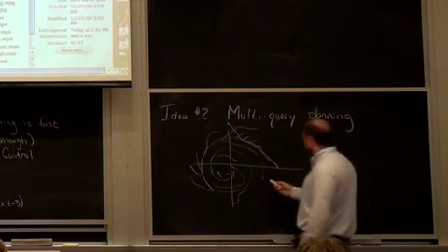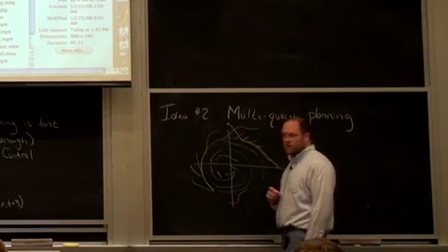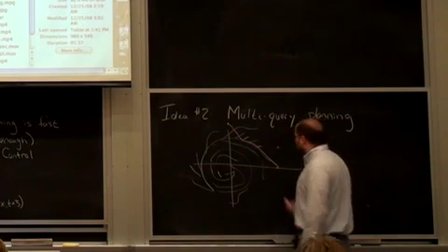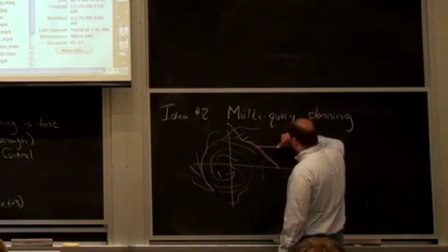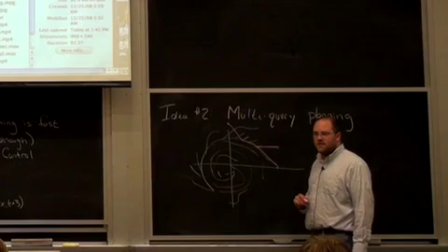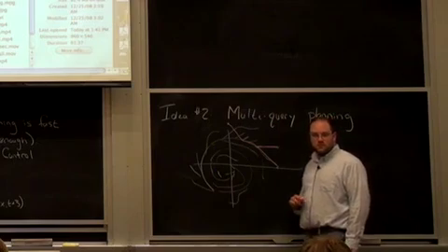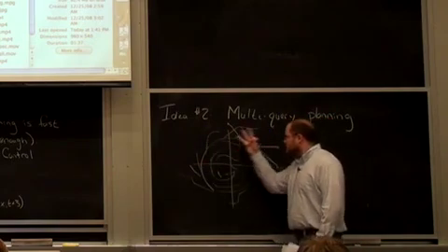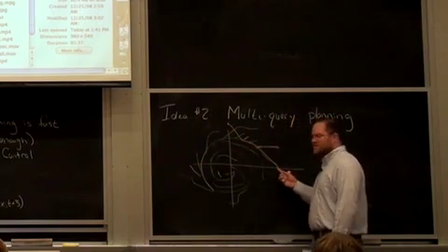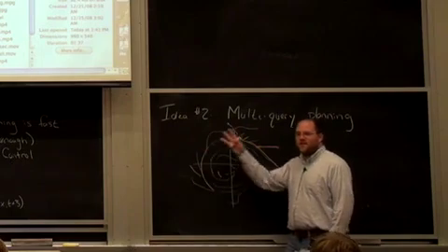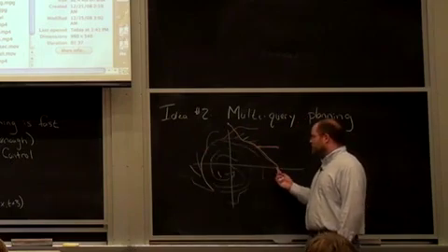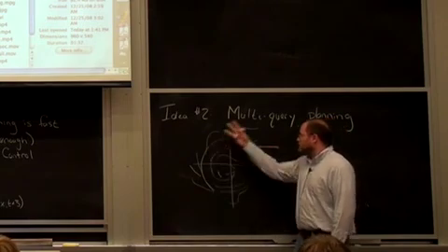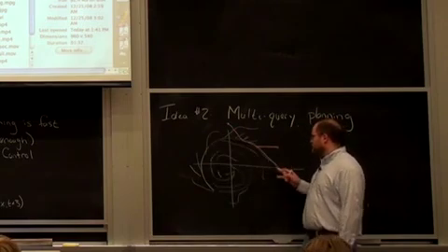Simultaneously, if someone were to tell me I want to get to a different goal, let's say I want to get the system to the upright with some velocity, all I really need to do is find a way to connect from my old plan to the new goal, right? So as you design these, the first start-to-goal planning problem, where you're designing trees that try to cover all over the place, could be potentially very painful. It might take a long time to find your way from start to goal.